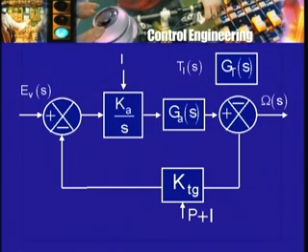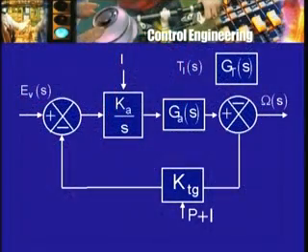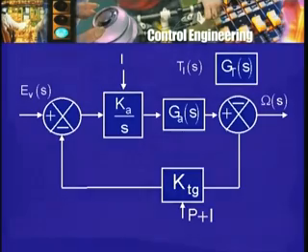So the whole block diagram corresponds to a linear arrangement. And in fact, we had shown that omega S is equal to ER multiplied by something, plus TL multiplied by something else, and therefore we can consider the effect of ER and TL separately. This is sometimes referred to as the principle of superposition, but it is also known as the property of linearity of the system. The system is additive with respect to the inputs, and it's multiplicative or homogeneous with respect to scaling of the inputs.